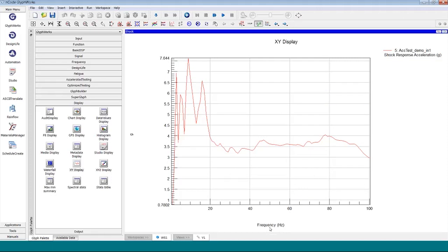Now this is often used for designing electronic parts, for example, your cell phone. What's important in a cell phone is that you should be able to drop it and pick it back up and it still works. You drop it again and pick it back up and it still works. Now if you did that 1,000 times, shame on you, and you wouldn't expect it to work. However, you expect it to be able to withstand peak G loading a few times. If that was your design metric, the shock response spectrum, the worst case G loading versus frequency, can be a very useful design metric. But what about the accumulated fatigue damage, not the worst case, the fatigue side of inertial loading?